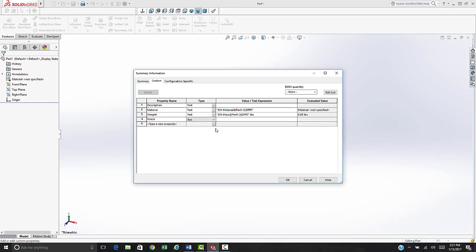I'll also add a finish on there if I'm doing an anodize or a nickel plating. I'll come in and change all this. There's no finish callout here, but you can just type in here, if you're going to do an anodize, whether type 2, type 3, and the color. You can add all that information in here, and that will show up on your drawing.